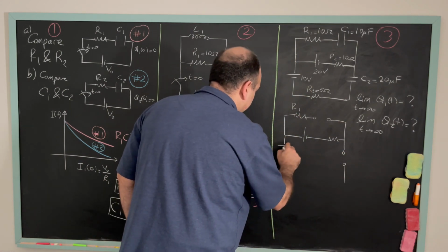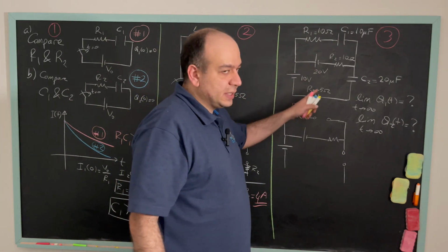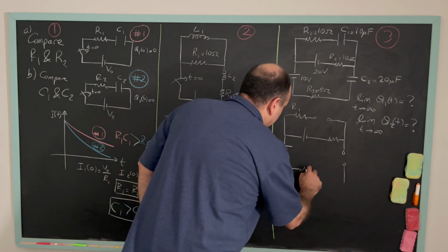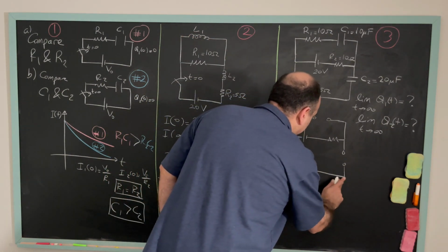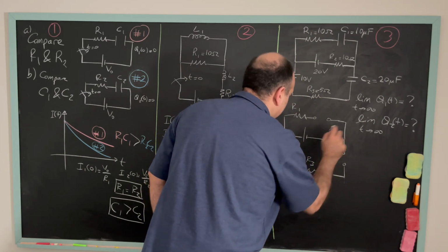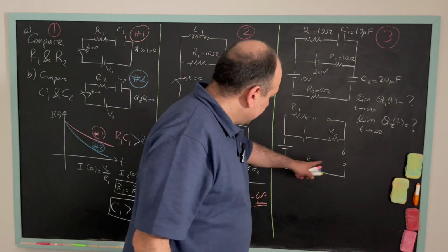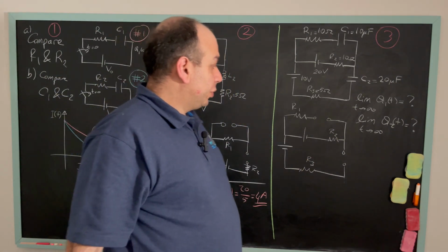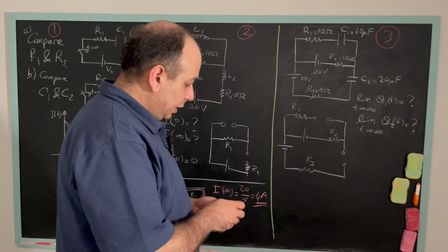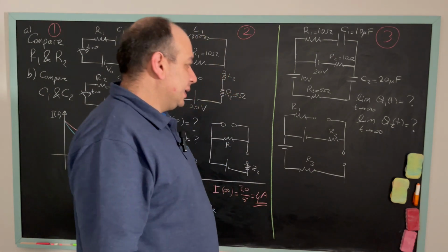There is a battery here, another resistor, and I'll have another open here. I'll have a 10 volt battery. We need to be really careful with the polarities here. Okay, and then I'll have another resistor here. I call it R3, this is R2. We do not see any closed loops here, so there will be no current running through any of these branches.